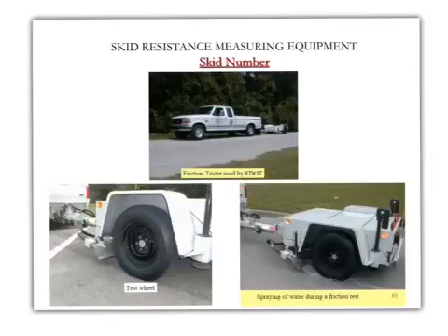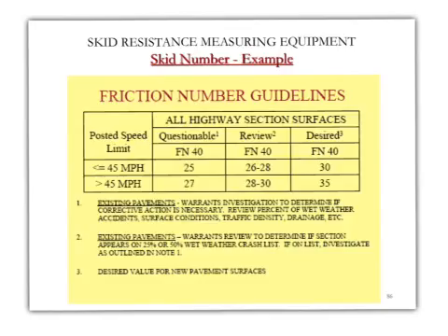And now, as you could see here, very interesting, we have this little instrument that sprays water during the friction test. Once I apply water, all of a sudden I will apply the braking forces, and then I will take my measurements to determine the skid resistance for that road. Once we do our measurements, the question now is, what are the minimum skid resistance numbers?